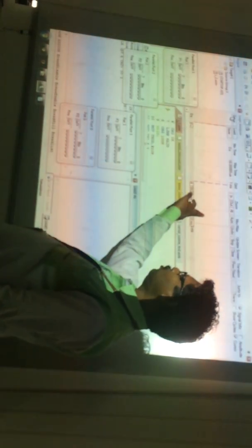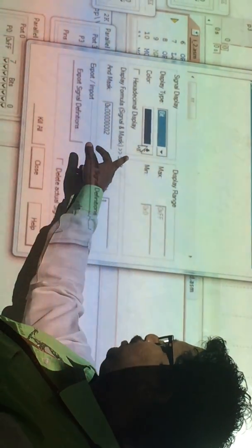Starting. Okay. So what is the setup we have to do in the logic analyzer for the waveform? We are going to have this setup. Which particular port do we have to have? That we have to select: P3.1. P3.1 we are going to assign. So delete if you have repeated. You can select bit. Okay, again P3.1. You can select that particular thing. Instead of analog, select bit. Okay. So in that bit, you select the color coding. Okay, over everything. Close. So this has been configured.